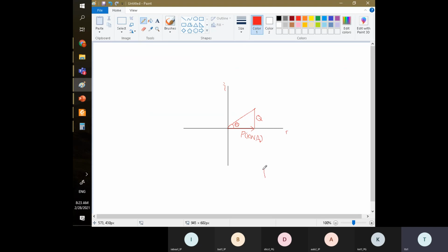So we write P, the real power, plus or minus the imaginary jQ. So we write j imaginary Q. And then the longest line here, the resultant power, is called S. It's called the complex power.